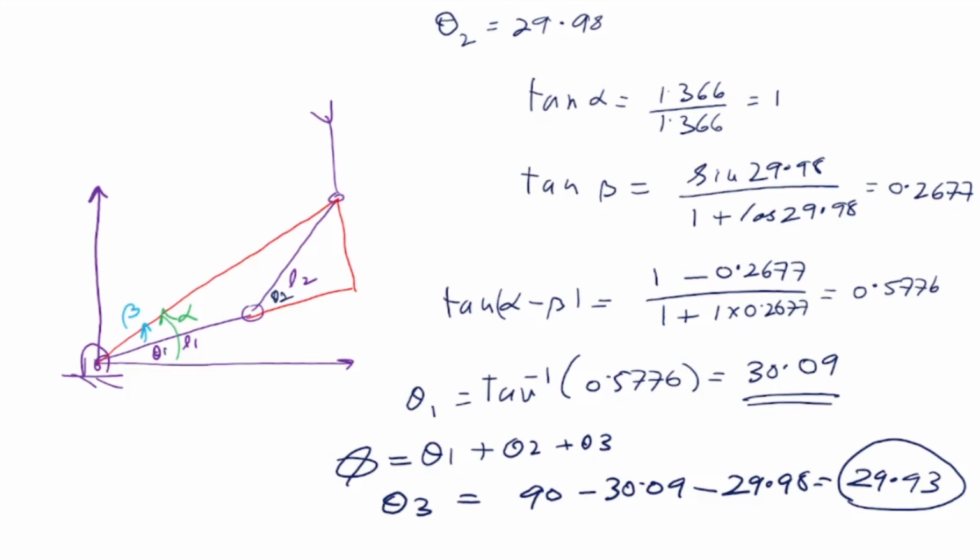This numerical problem comes up in inverse kinematics, so you have to be a little careful. It also means the controller will not get an exact answer. It will be a rounded off answer, very close. So it will not be 30, it can be 30.005 or 29.98, because of the sine and cos terms.